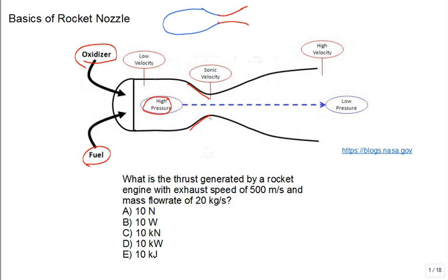But if you just stop right there and you don't have that red section, it will only come out at the speed of sound, at that temperature that it comes out at. But I want it to come out even faster. I want it to come out supersonic. Well, the math and the experimental observation say what you can do is gently expand the cross-sectional area. Professor, that's going to make it slow down. That's a diffuser. But you're feeding it Mach 1 air.